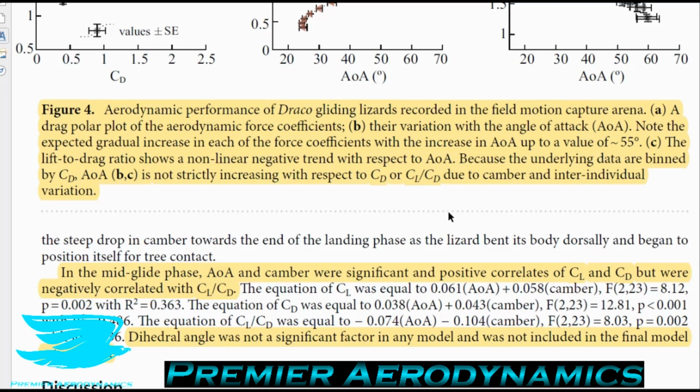And there's also the effective angle of attack that the wing sees, which I'm not going to get into. I'll probably do a podcast on dihedral angle at some point, but we don't need to worry about the effective angle of attack. Just think that the flow that the wing is seeing is at a lower angle of attack than what you'd expect it to be based on geometry.